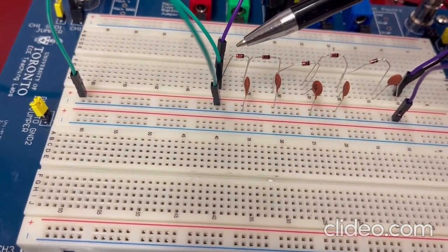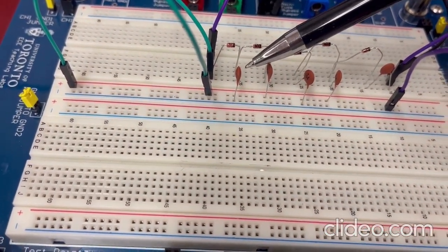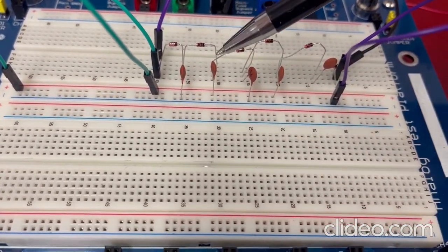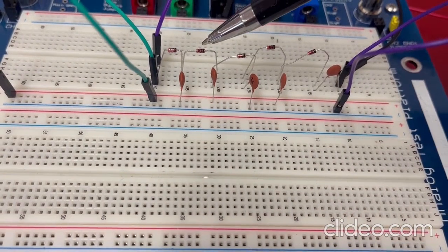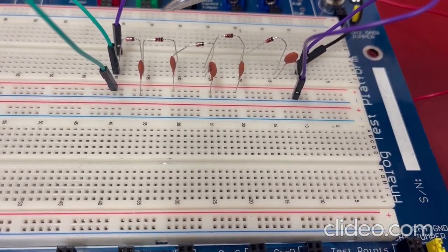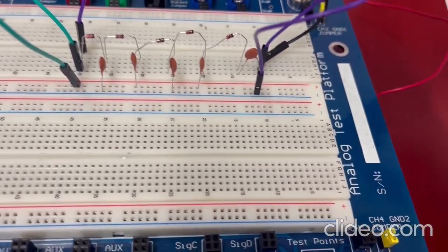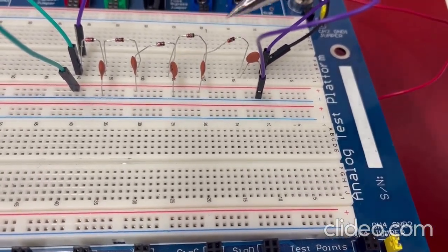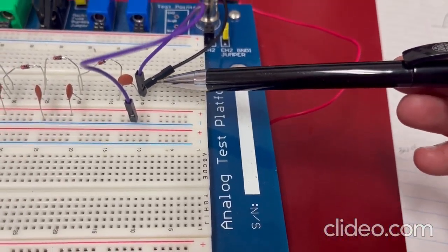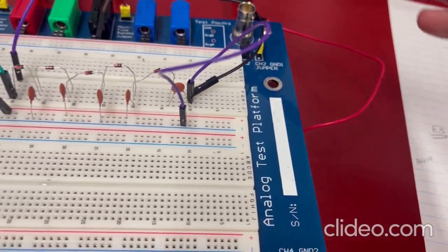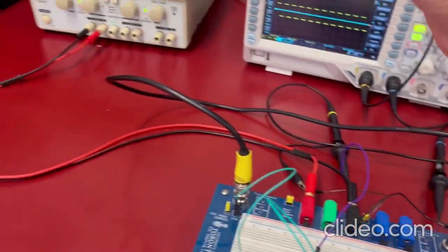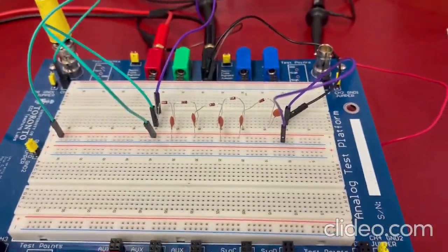Cross check your polarity. This is P, this is N, and now this is C1 from this to ground, and C2 is between diode D2 and the signal. So cross check these connections. I have D1, D2, D3, D4, D5, and this is C1, C2, C3, C4, and C load. For the C load, I have used the ground of my supply, which is connected to the ground of my supply.